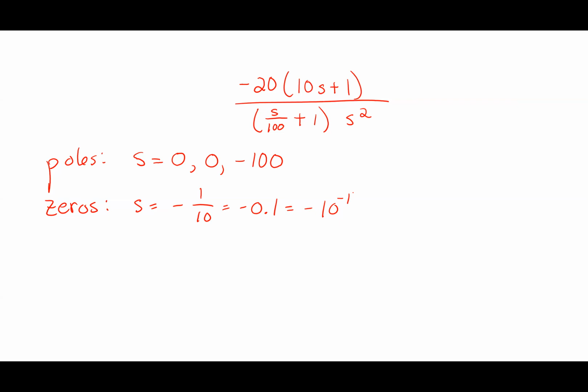All right. What would be the corresponding breakpoints? So I'd have basically omega p values and omega z values. What are my breakpoints? Basically, those are the points where the graph changes, right? So what are the points where the graphs change? Yeah, so here it's 0 and 100. And if you told me 0 twice, I'd take that. That's fine. Omega z, what would that be? 10 to the minus 1. All right.